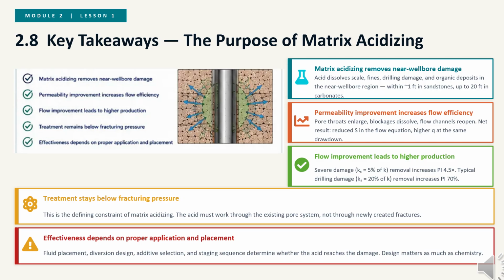But everything depends on control. Stay below fracture pressure. Use the correct formulation. Control placement. If the acid does not reach the damaged zone, the treatment fails. If the design is wrong, you can make the well worse. So take this as the rule. You are not pumping acid. You are removing a restriction.